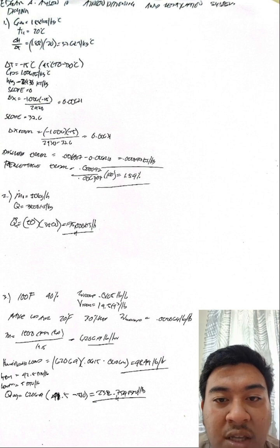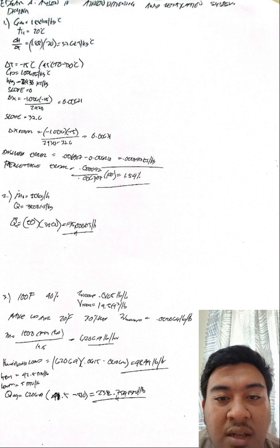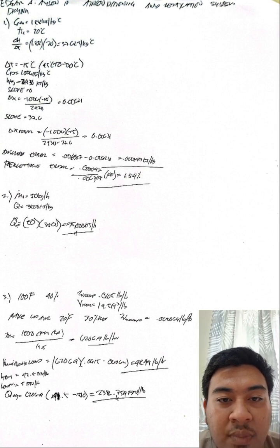That's the minimum heating coil capacity needed, and increasing preheat by 10 degrees Celsius does not help a bit, because most of that extra heat just leaves with the exhaust as waste.